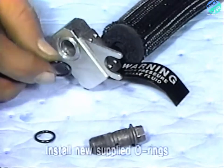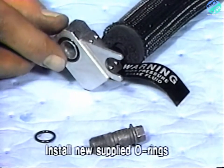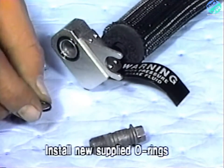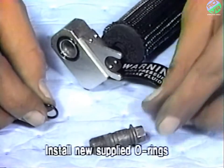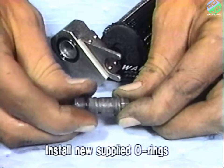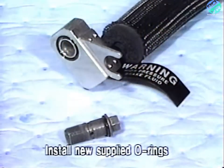Next, lubricate the supplied O-rings with brake fluid and install the large O-ring on the connector block face and the small O-ring on the cleaned banjo bolt. When working with brake system parts, keep your work area clean in order to avoid contamination of system components with dirt or foreign materials.